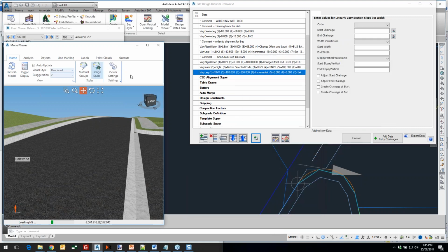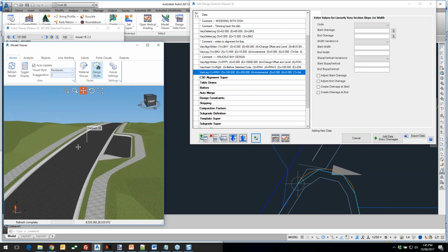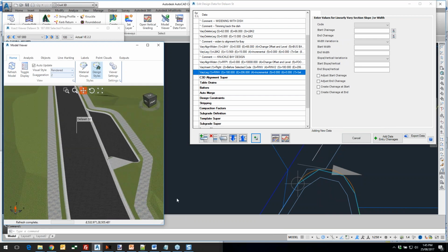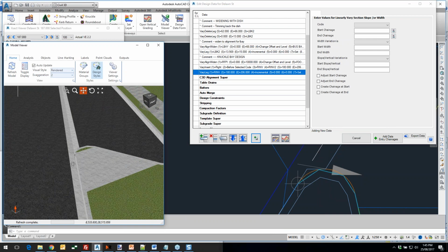So I don't really need to play with that at this stage. Okay, so we've actually done option 2 here. Just realize as well that this is concrete because it's back of curb, running to back of curb. You could fix that up from a modeling perspective by putting a little code in here called bat or batter, so that it did actually batter.